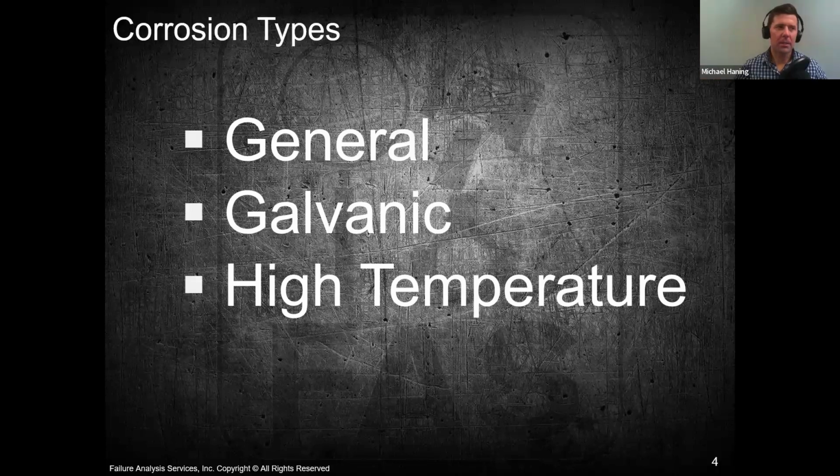Let me ask you a question about location and humidity. If you're in Houston on the coast versus where you are in Colorado, how does that play a factor in general corrosion? So humidity plays a factor. Ambient temperature, or the temperature that the component parts are exposed to, plays a part in it as well. Not just the high humidity, but in Houston we're fairly close to the ocean, and there's a lot of salt in the air, which causes that moisture in the air to be a more aggressive electrolyte on some component parts, accelerating the corrosion. Good question.